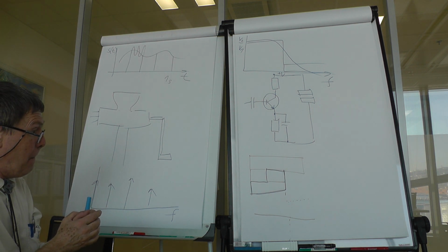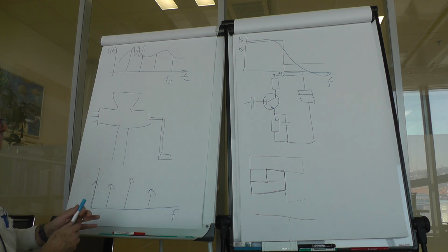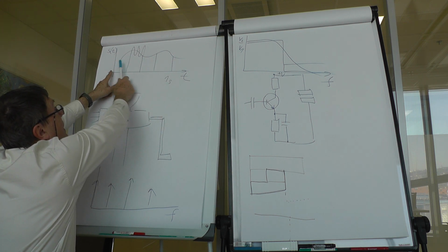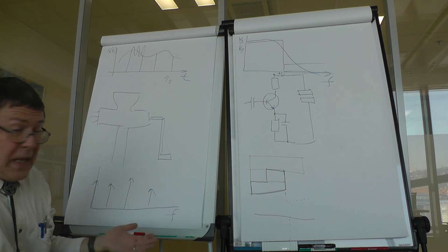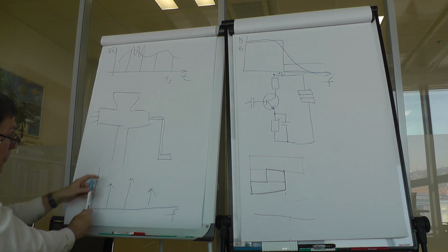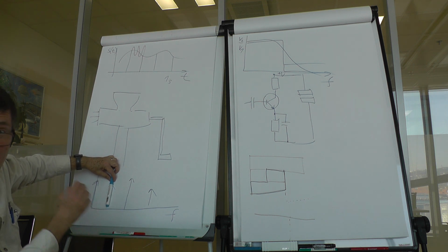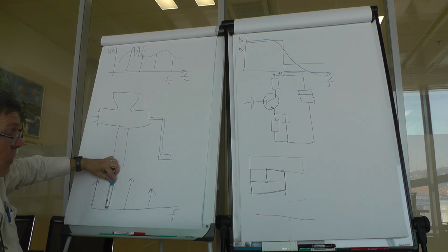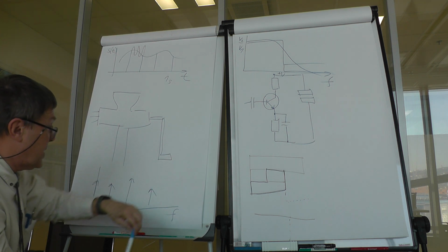Now, a few minutes ago I told you that if I have 1 second of samples in time, I have the first harmonic at 1 Hertz in the remaining signal, or I could get it. It could be 0 for certain numbers at the input, but anyway, I can get 1 Hertz. The second harmonic would be 2 Hertz, 3 Hertz, 4 Hertz.